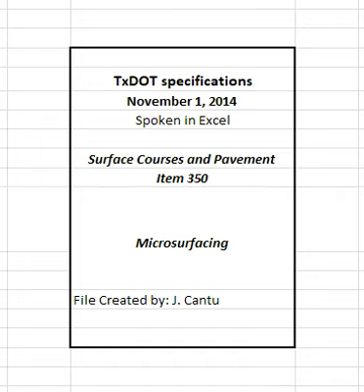5. Measurement. Microsurfacing will be measured by the ton of the composite microsurfacing mixture, which includes asphalt emulsion, aggregate, and mineral filler. 5.1 Aggregate. The quantity of aggregate used in the accepted portion of work will be measured by net ticket weight of each individual load of aggregate based on dry weight of aggregate.